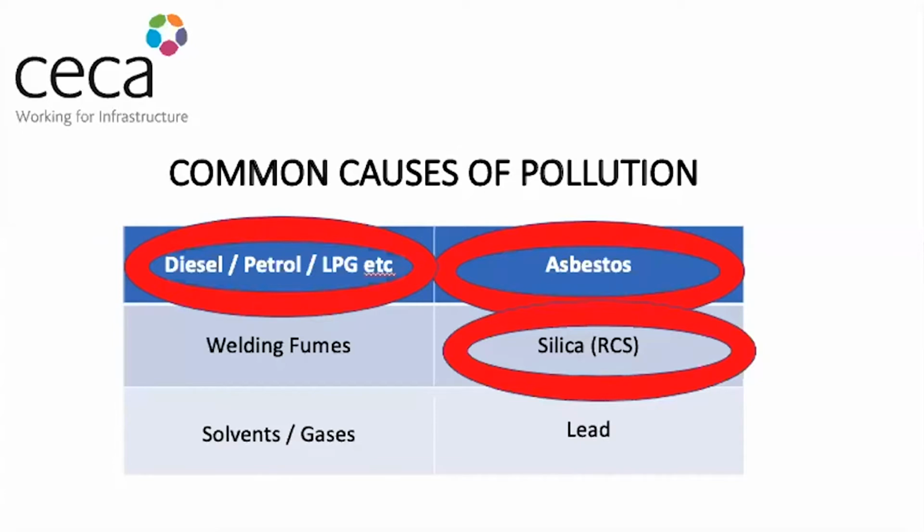So looking at diesel engine exhaust emissions, these are likely to, as we all know, come from generators, heavy vehicles and lorries, excavators, and telehandlers and the like. The more significant risks are linked to longer periods of work with the equipment, particularly in enclosed spaces, and in situations where there is black and blue smoke, which I'm sure we've all experienced sometime in our life.